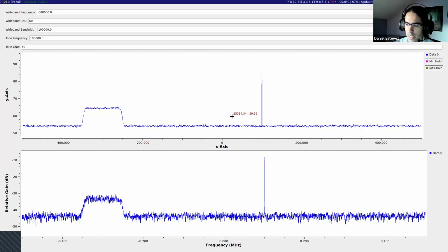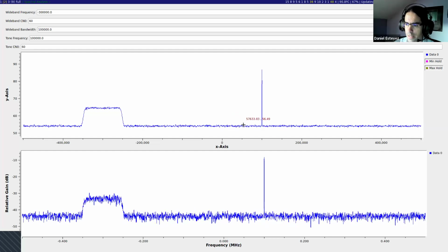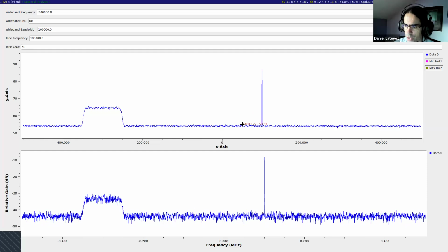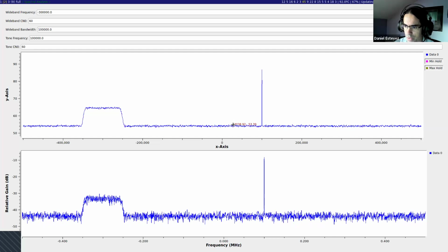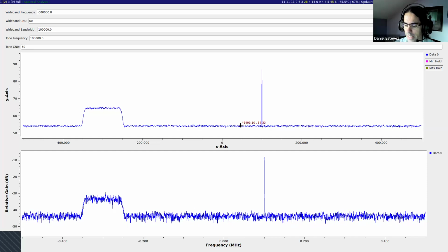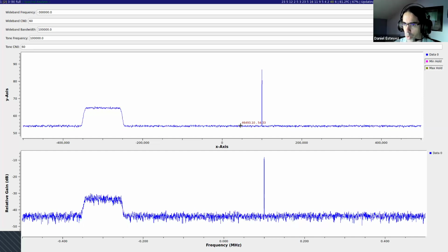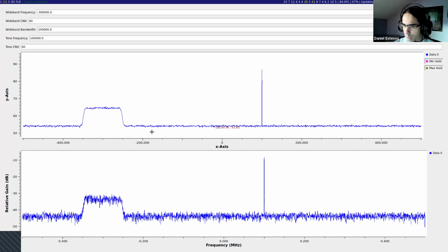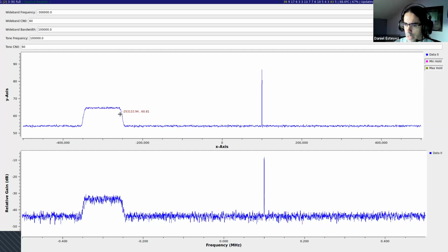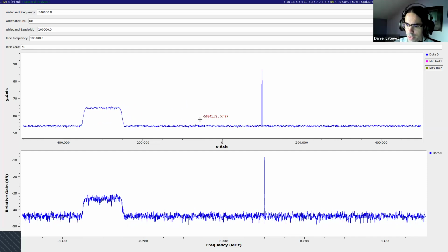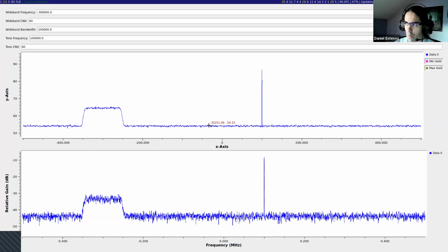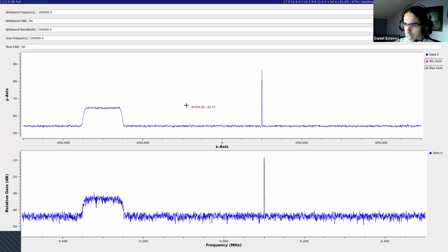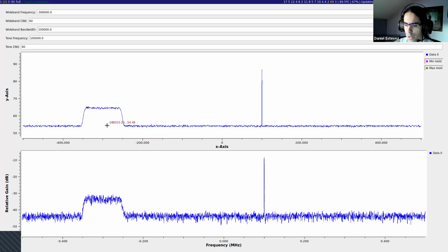Or another way of saying it, the signal to noise ratio we get on this, or how spiky or irregular this noise floor is, decreases with the square root of the integration length. So yeah, the square root is annoying because to get this twice better, we need to integrate 4 times more, but it is how it is.